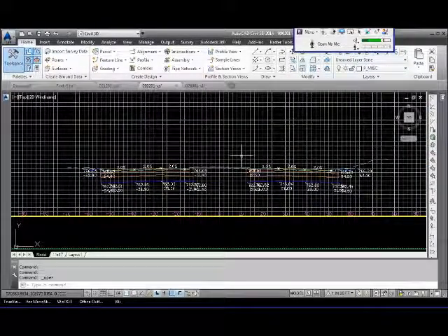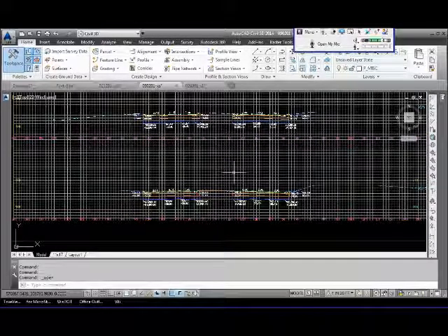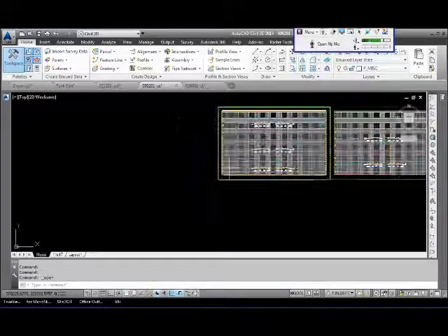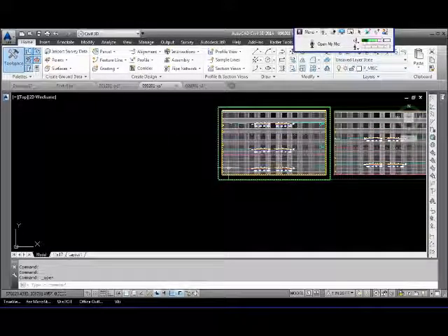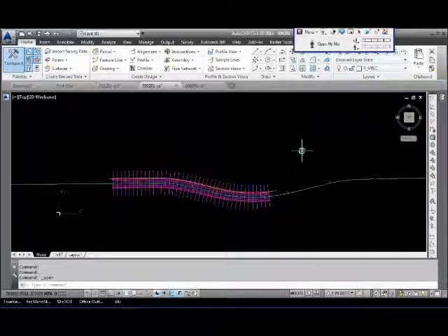There are a few ways it can be done, through a profile grade add on a sample line or what have you, that actually really slow you down. If you want to add one, it becomes extremely difficult to add that to your profile grade. So I'm going to show a quick way to add markers onto section views that's dynamic, that you can add and remove one at a time, whatever you want. You can add or remove per different section view if you want to, and that's with feature line projections. That's what we found is the easiest, and it's completely dynamic.